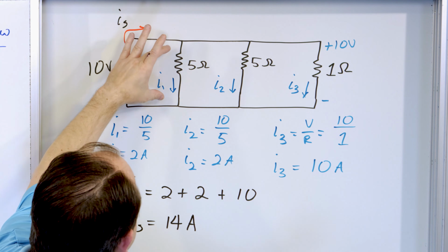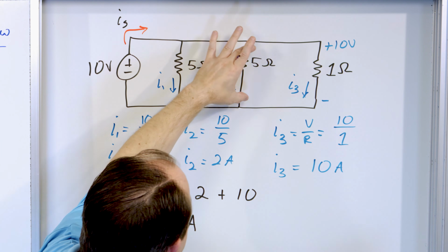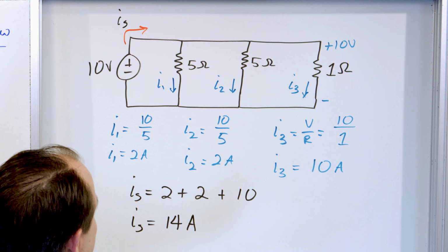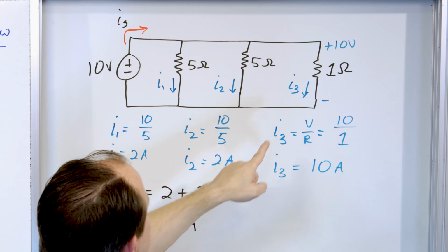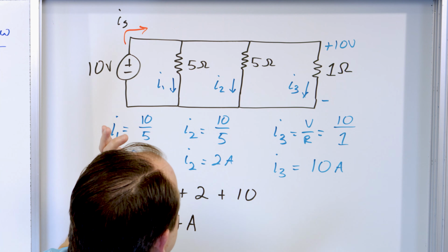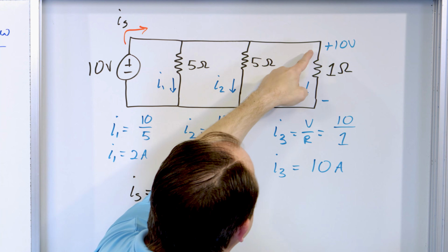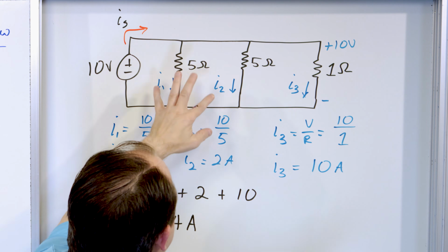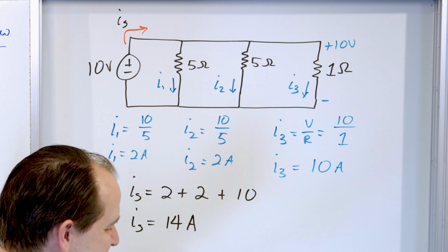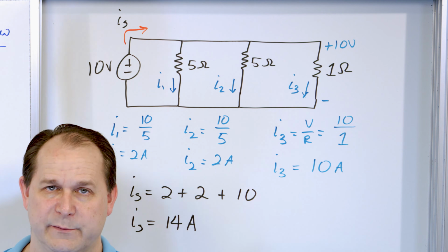And the voltage across each of the items in parallel are exactly the same. That's another important difference. And the last thing is that if you have items in parallel, the current will split in such a way so that most of the current flows through the lower resistance items, and relatively speaking, less current will flow through the other higher resistance elements.